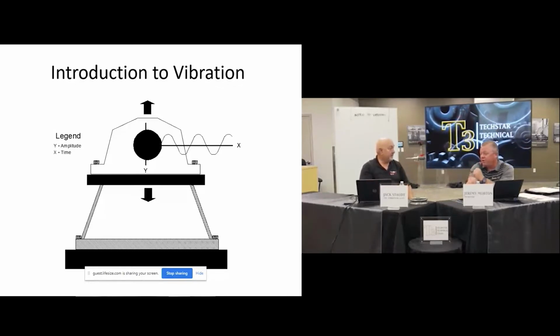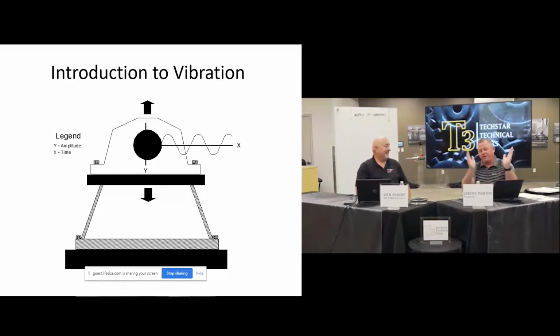And that can get a little confusing when you're going through a gearbox or anything, but as long as you always keep the driver at your back and the equipment that's being driven to your front, X and Y always holds true. Absolutely. Unless somebody's gone in there and switched a few wires. Yeah, I know early on when it's a 45 left and right and you're thinking horizontal and vertical, it can kind of throw you off. Or if they're underneath, on the bottom half of the bearing for whatever reason, that can throw off a lot of people. Absolutely. That's a good point.